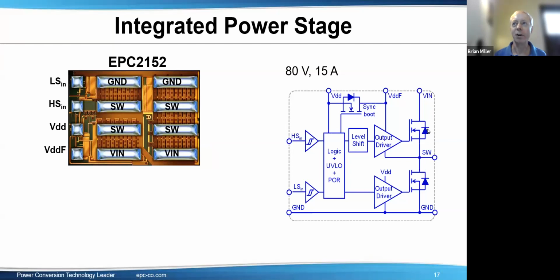That's not really needed because there's no reverse recovery in the GaN FETs and the diode here. But also, going back to the question, a Miller clamp is a clamp that comes down to keep the device off when the other is coming on. You need something, because if it's open circuit, it could come on. So you want something that holds it off at 0. But I don't think you need special, sophisticated external clamps on it.